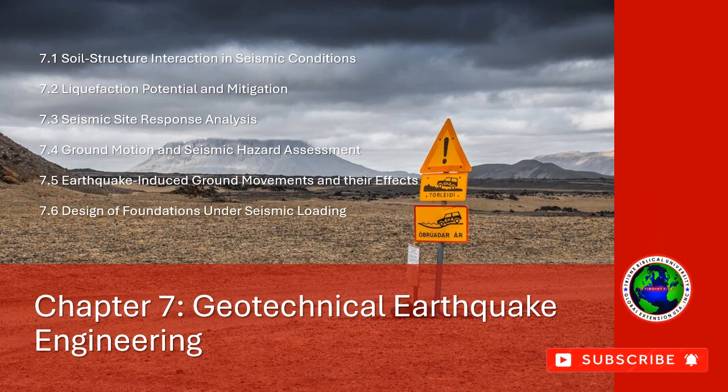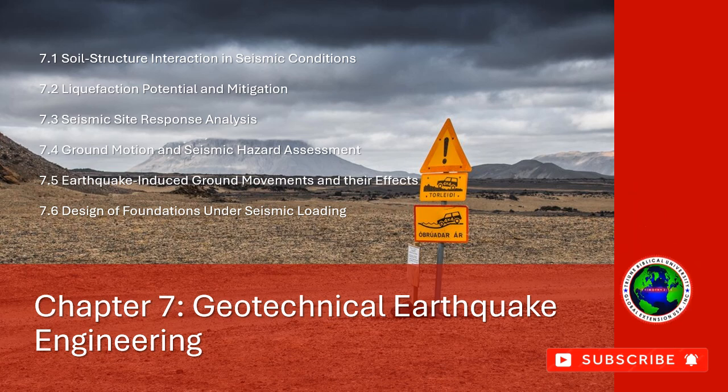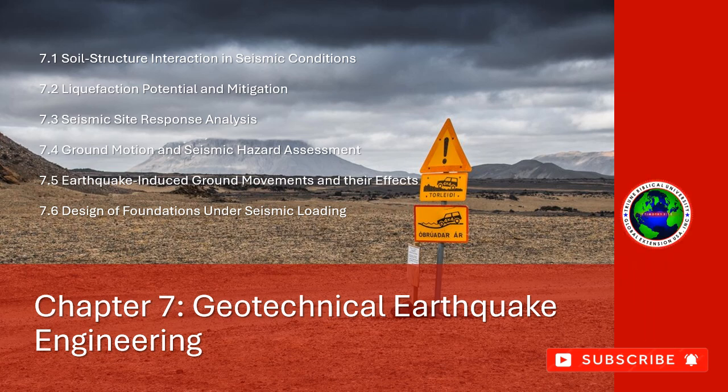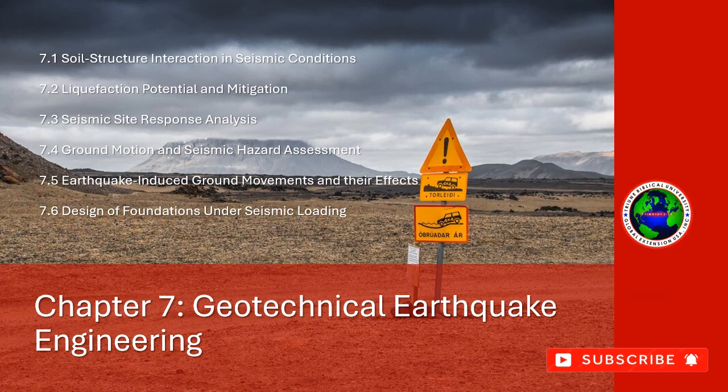7.1.1 Key Concepts in Soil Structure Interaction. Soil structure interaction involves the dynamic interaction between the foundation of a structure and the underlying soil during an earthquake. The interaction can result in changes in the structure's response to seismic forces, such as amplified vibrations, settlement, or tilting, depending on the soil's properties and the type of structure.